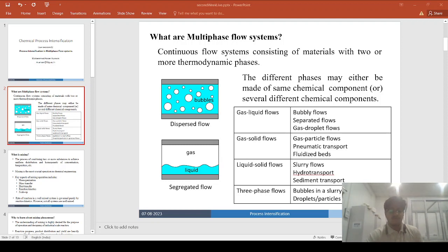You will have some solid particles that have absorbed some moisture, and if you want to dry them, you make hot gas pass through the entire batch of the particles, so that the gas phase can carry the water vapor that may evaporate through the gaseous phase. That may lead to the drying of the particles.